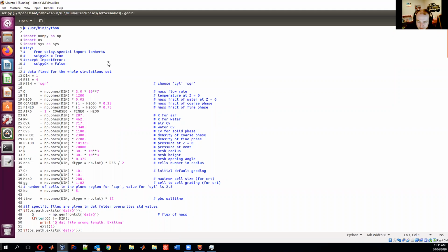As you recall, there's a whole lot of parameters here that we can change, so let's just run through them again. Res, recall, was the resolution of the mesh. Sorry, that's the resolution of the mesh at the vent. At the moment we've got 4 cells spanning the vent. I'm just going to change it a little bit to 5. I don't want to make that too high because it'll probably slow my computer right down. But I also want to get a little bit more information about the accuracy of my simulation.